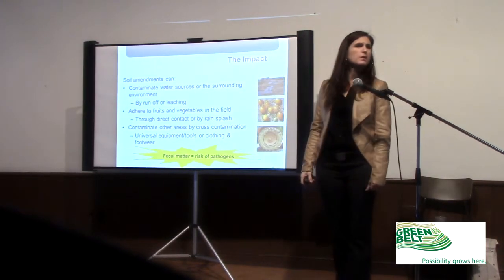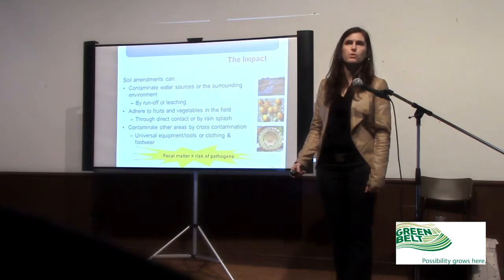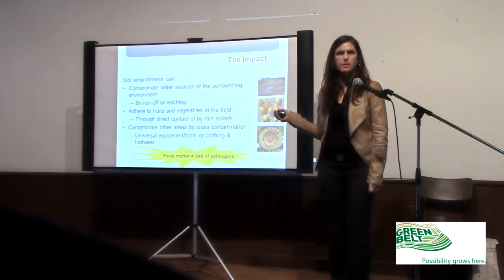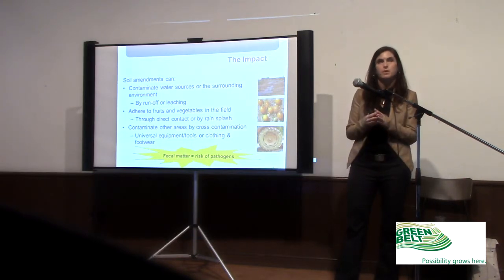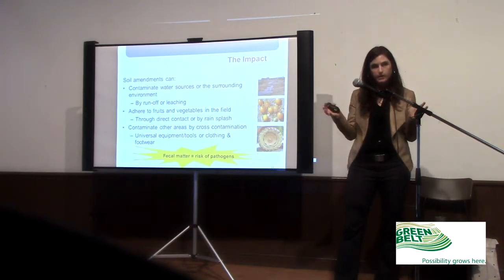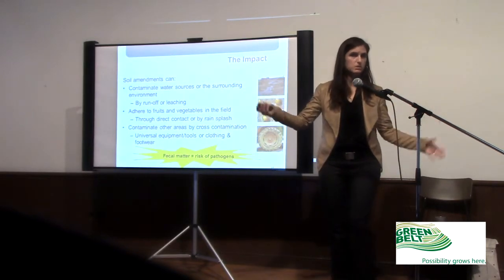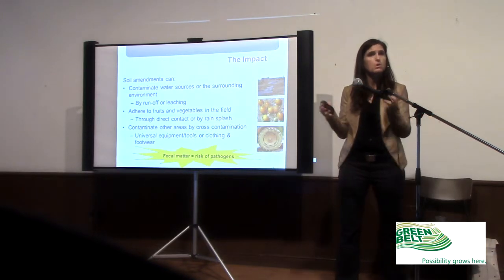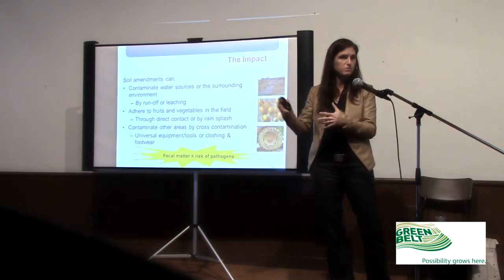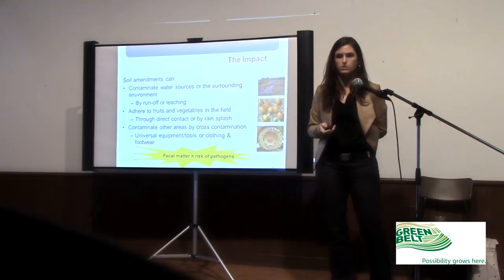What's the recommended distance from your compost manure pile to open water? For open water, we have a slide on it. I believe it's 50 meters. A general regular buffer area is a minimum of 3 meters, but when you get some of those sensitive areas, it increases a lot. That does depend on whether it's a permanent storage site for your manure compost, or a temporary one, if you might have mounds in the fields, and we discussed that a little bit. You will have that reference slide in your book.